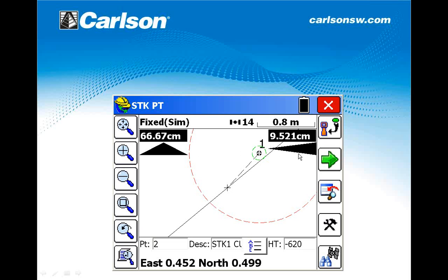Okay, so we make our first try with the pole in the ground and see, it is like 66 centimeter in front of me and a small correction of 9 centimeter to the left. So I make my second try. I visualize on the ground these distances aligned with my face, let's say, just in front of me, one line 66 centimeter and 9 centimeter to the left.